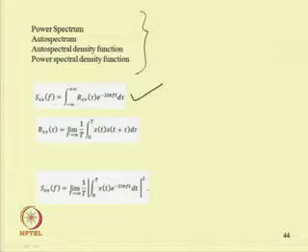So, one can use this equation, that is S_xx(f) equal to integral from minus infinity to plus infinity of R_xx(tau) e to the power minus 2 i pi f tau d tau, where this R_xx is known as the autocorrelation function, which can be given by this expression. So, R_xx(tau) equal to limit T tends to infinity 1 by T, T being the time up to which we are finding the spectra, integral 0 to T x(t) x(t plus tau) dt, where tau is the delay of the system.